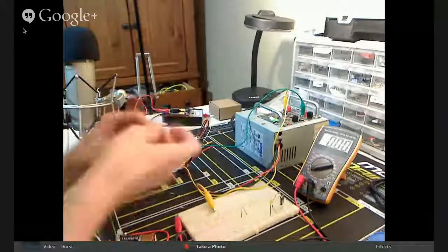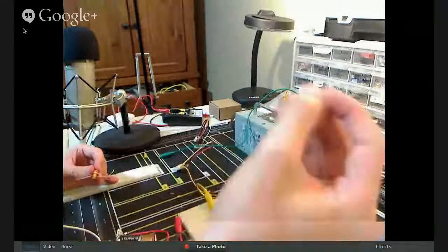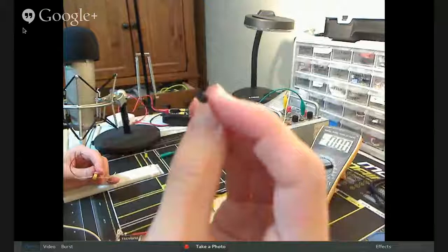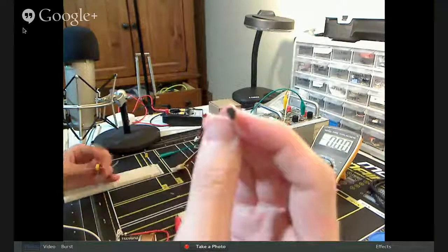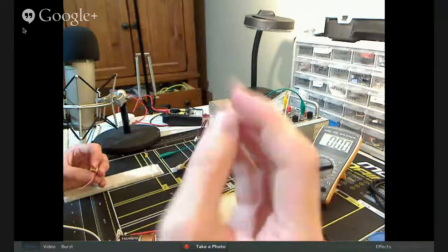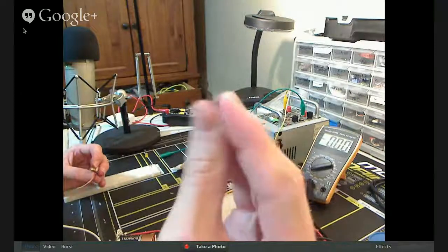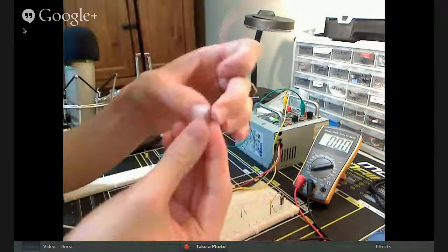Right, and you'll need a transistor. This is a transistor package. Transistors come in different size packages. This is a TO92. It's a very common package. We call it through-hole construction, because on a circuit board, these leads would go through the circuit board and then be soldered on.